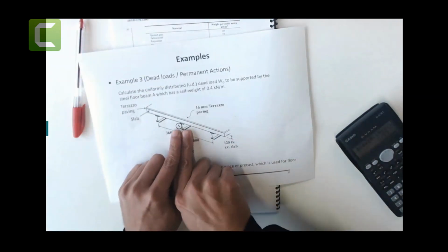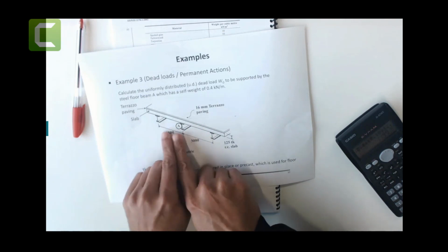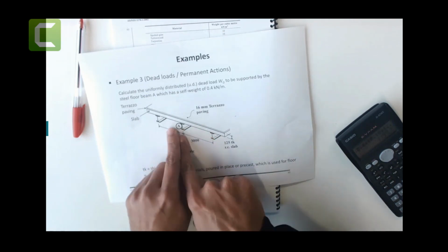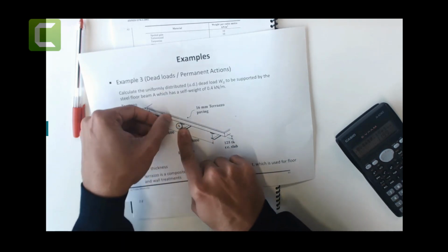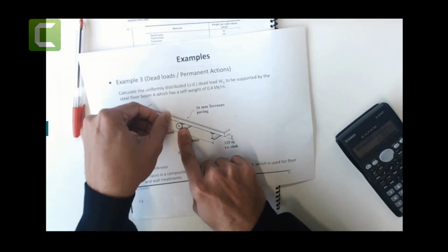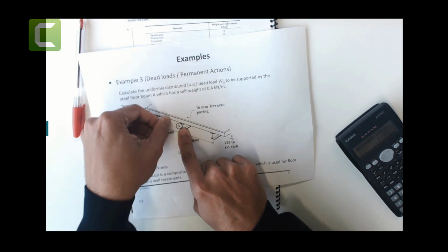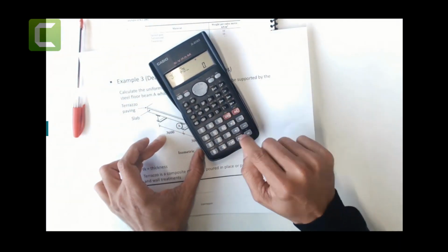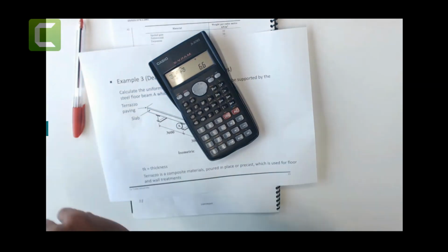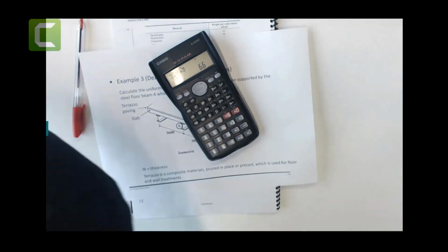If you come across this kind of sharing load between the beams, you might need to calculate the floor. I think they use the vocabulary tomorrow in the workshop. I will tell you that vocabulary: you just need to calculate half goes here and half goes here. So you can't just take 3.6 plus 3 and put 6.6 here, that would be wrong.